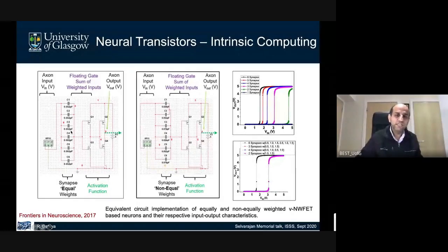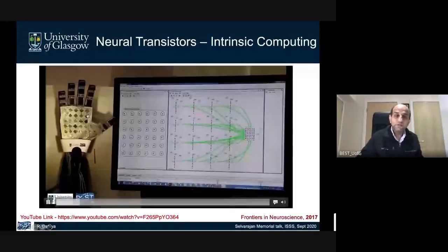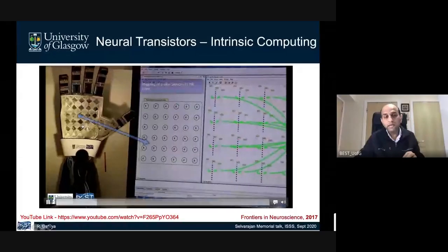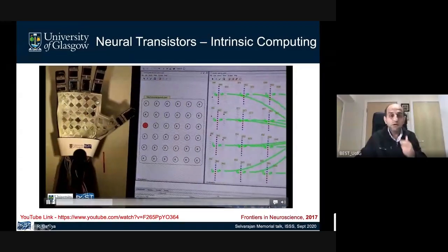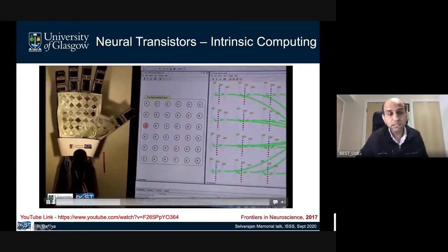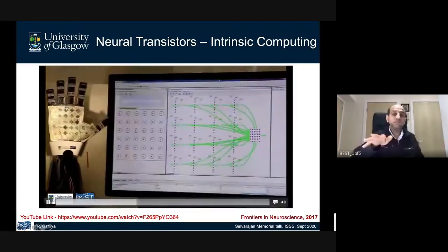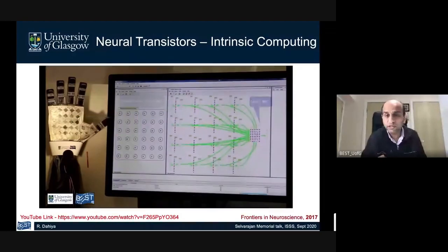They do not change. And in that regard, we have also done some work. I'll come to the next slide where this is explained. But before that, I would like to show this implementation using the neural nanowire FET model that I presented earlier. What we did, we developed a 6x6 capacitive sensor array, and the output from this sensor array was fed into the multiple gates of the neural nanowire transistor.